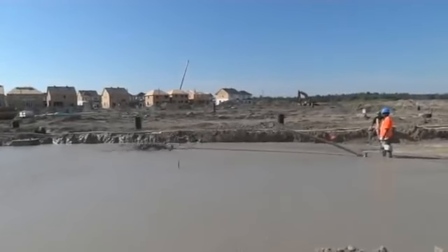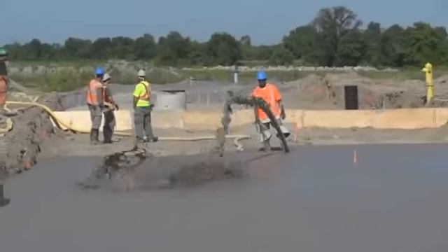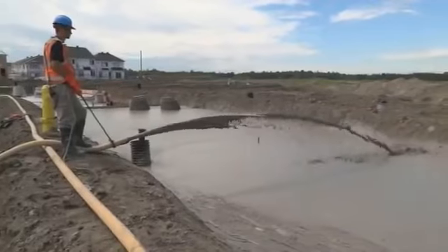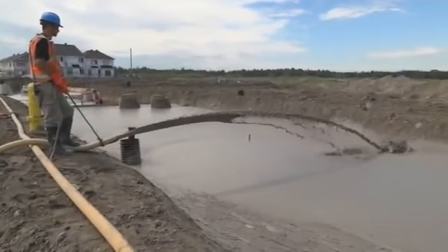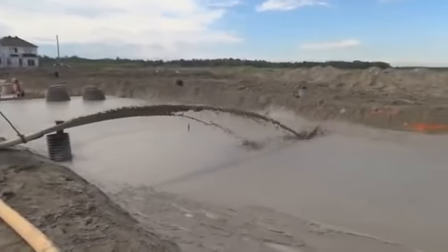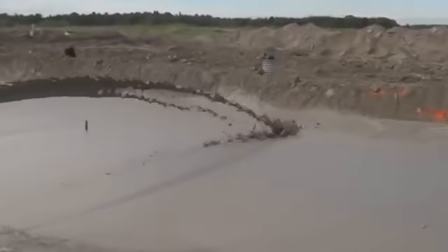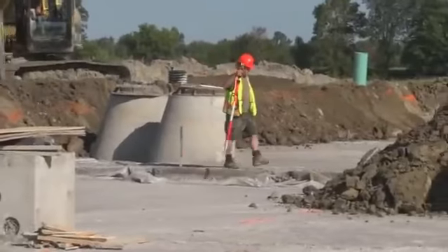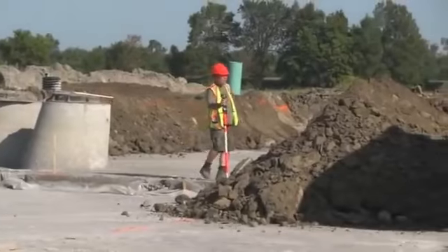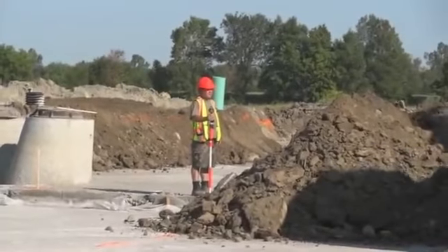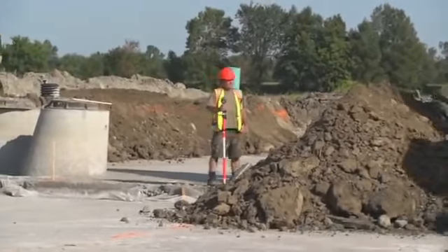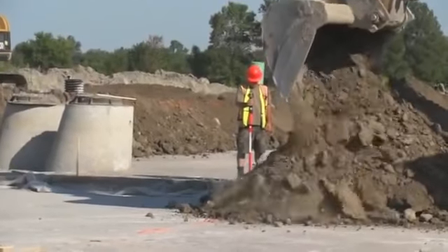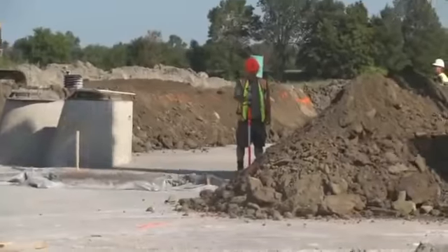Cellular concrete considerably reduces, and in some cases completely stops, the influence of moisture on the structure, frost heaving. Cellular concrete forms a harder foundation if compared with gravel, which is an obvious advantage. The weight of the structure is greatly reduced, which is effective on weak sand and wetlands, and at the same time the thickness, depth of the road foundation is considerably reduced.